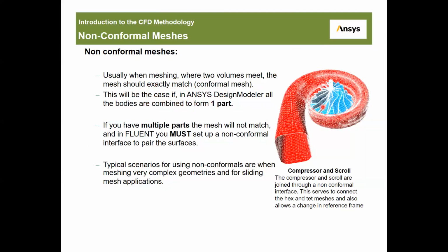For example, you have this turbine housing, and then you have the propeller. So this propeller and this housing, you have two bodies. It's different bodies, but we must combine them in terms of mesh. So the mesh conforms to each other, so the nodes meet at the interface of the machine.